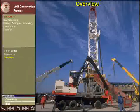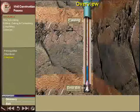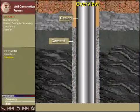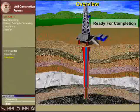After the well has been designed and the well plan written, it is time to begin the actual construction of the well. In this module, we will trace the sequence of operations that are undertaken in order to construct a well. Well construction begins with the processes of drilling, then casing. The hole is drilled in stages, and at the end of every stage, casing is put into the hole and cemented into place. After the well has been drilled to final depth, and all of the casing has been cemented into place, the well is completed.